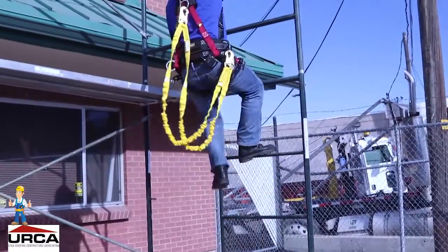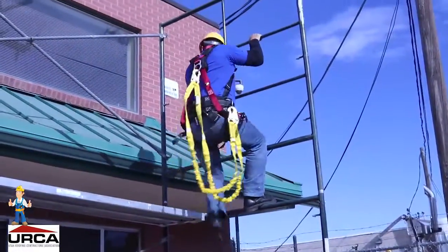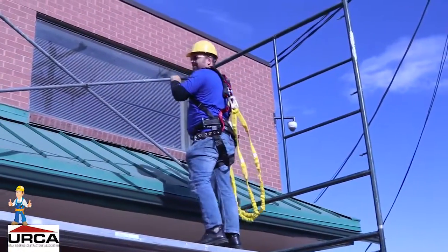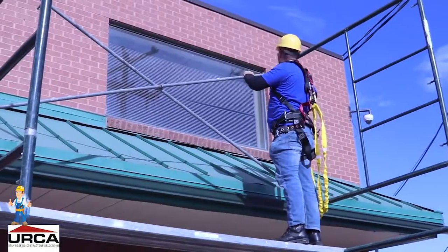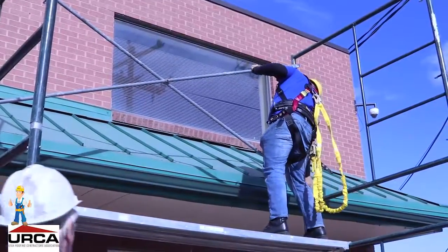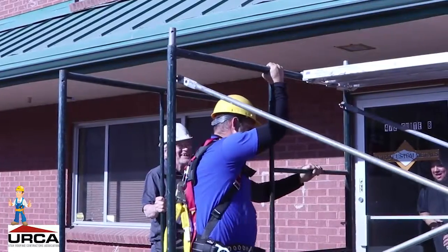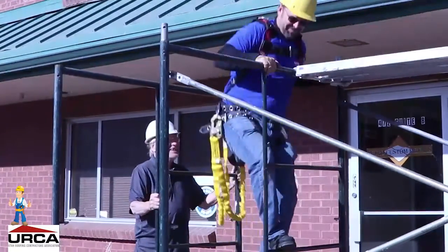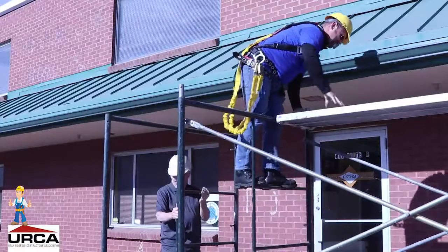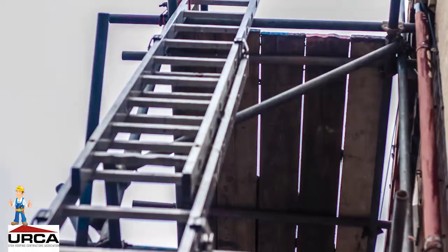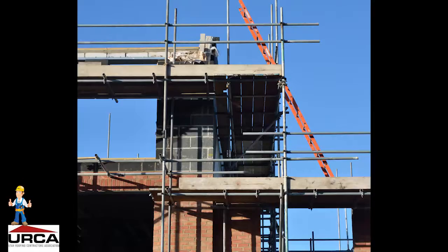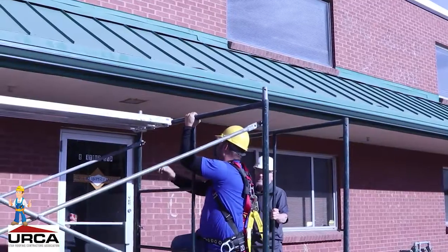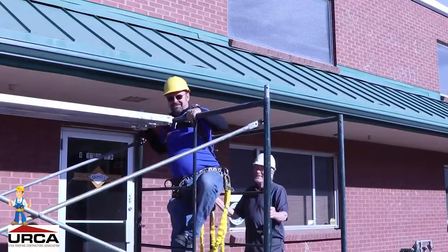Chances of injury are highest when climbing onto or off a scaffold. Never use a scaffold unless approved by a competent or qualified person. Safe access must be provided to all scaffold platforms that are more than 2 feet above or below a surface. There are many types of permitted access, such as portable and straight ladders, hook-on ladders, or fixed and direct access from another surface. Some scaffold frames have end frames with ladders.